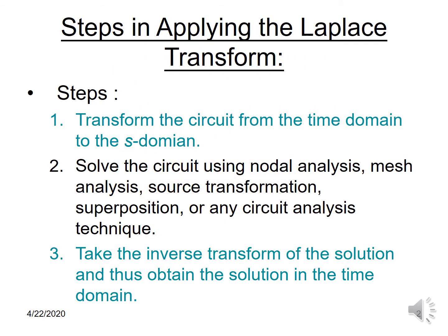Let's just revise the steps that are recommended to follow. First, we transform the circuit from time domain to S domain or Laplace domain. Then we solve the circuit using any of the analysis techniques that we have learned. And then we take inverse Laplace to go into the time domain.